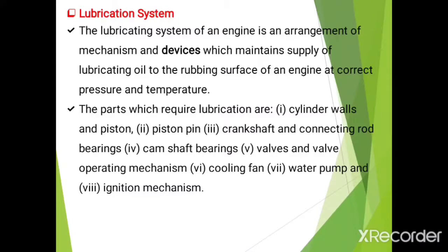Then it forms a good seal between the piston rings and cylinder wall, preventing leakage of the gases from the combustion chamber. Also it acts as a cleaning agent to carry away the dirt particles of the carbon and other foreign matter to the sump. Then it also reduces the power required to overcome the frictional resistance between the moving parts.